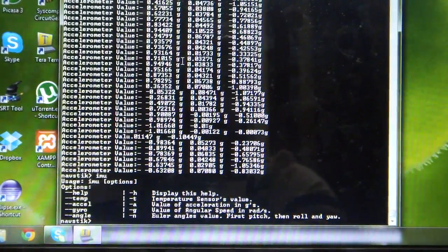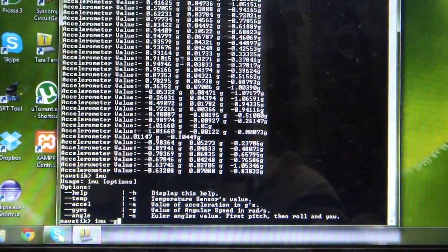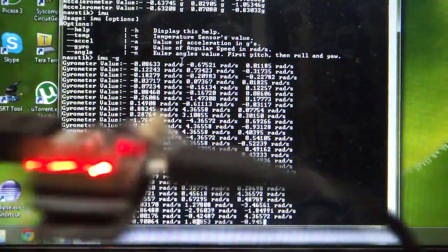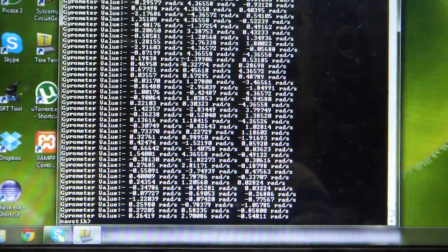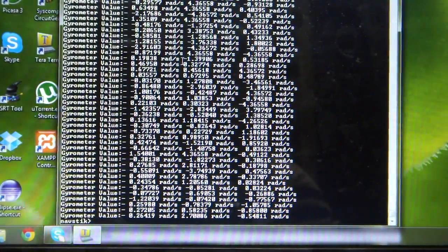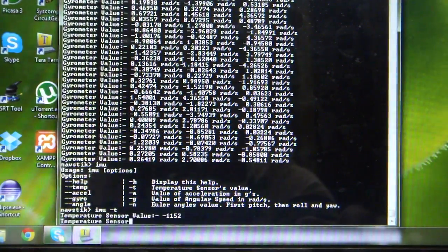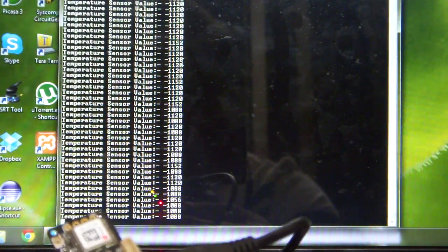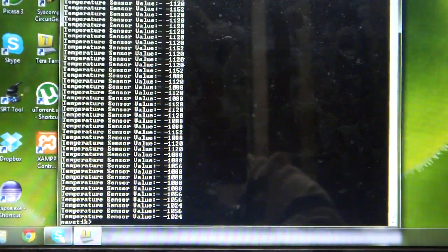Let's look at what else is available in IMU. We have the gyro option. This should show us the gyro data. It is hard to turn NavStik in a particular way to see the equivalent effect, but it can be put on a rate table or something and you can see what kind of values it is giving us. You can also see the temperature sensor data. This is the temperature sensor on the IMU. If I put my finger near the IMU, the values should drop. Yes, when I put the finger there, it reduces the temperature and we can see a drop in the readings.